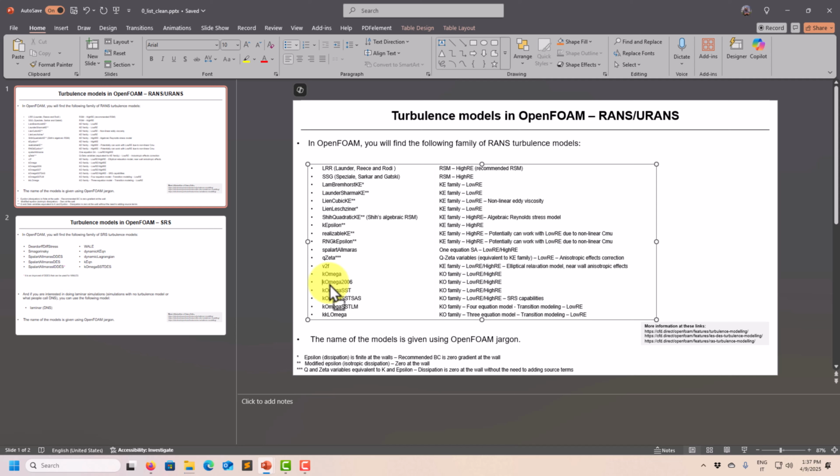Then if you want to get out of the K omega, probably Spalart-Allmaras. If you are working with, let's say, aerospace applications, airfoils, wings, and so on, Spalart-Allmaras is fantastic, but it's not limited to that. Winds and turbomachinery, you can also use it for bluff bodies and so on. Or you can go with the traditional K-epsilon, which uses wall functions, or the ones with the low Reynolds treatment. Okay, so it's up to you.